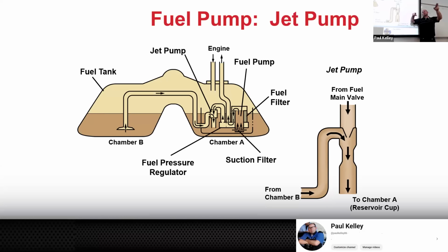Extended crank, especially after it sits for a while. So if you were to run it, shut it off, and start it right back up, it'll start quick. But if you were to shut it off and wait an hour and then crank it, it's going to crank for a long time, because the fuel had to make it all the way up there, right? So how do we replace that? That's in the fuel pump sending unit module assembly.